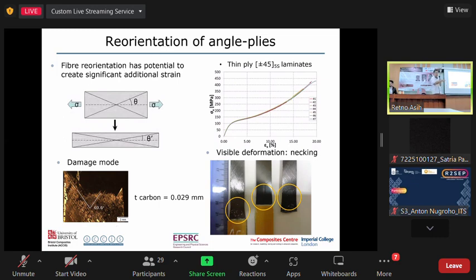So yes, does shear stress also play a role in QI? Well, I think mainly in angle plies you have the shear behavior. Of course, shear loading also depends on how you load the structures. If you do tensile loading, you don't get shear in unidirectional ones. Of course, you get some sort of shear in isotropic as well.